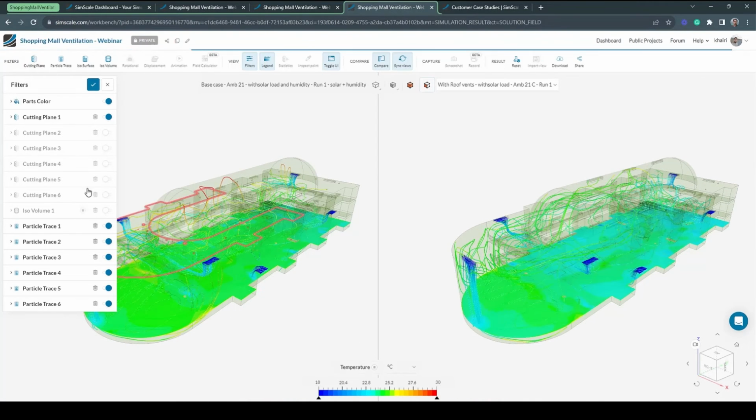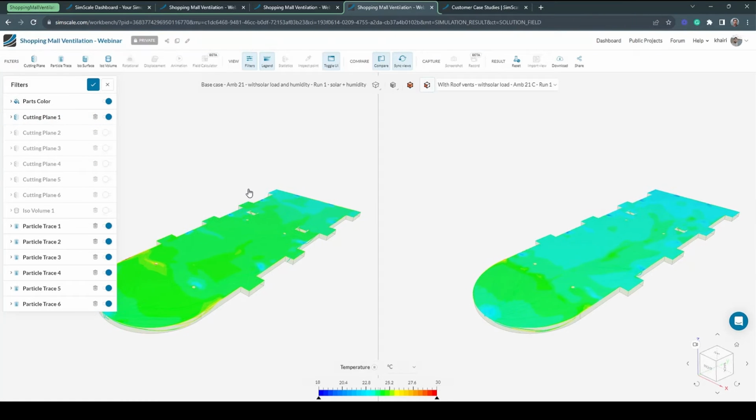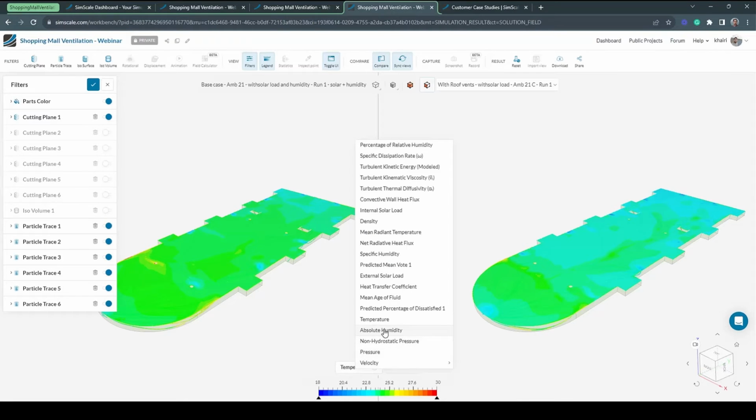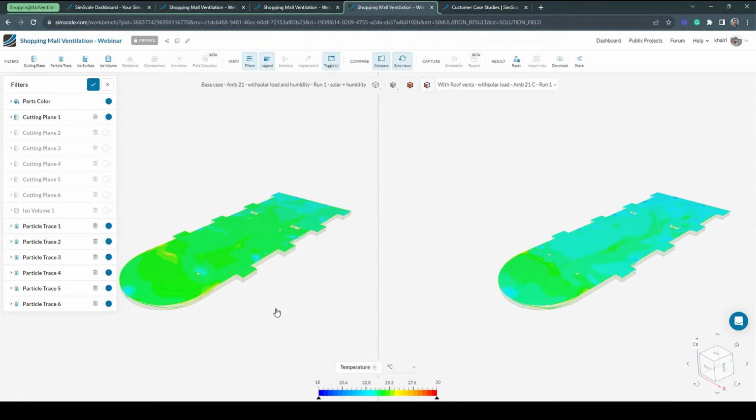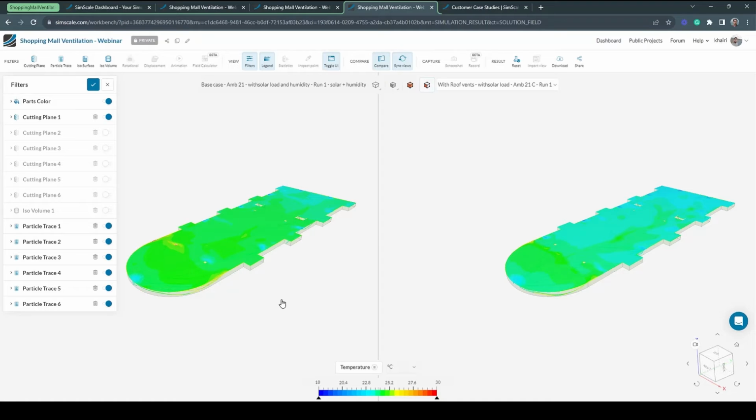And actually, this also brings me to the topic that with those simulations, the nice thing about CFD is that it really gives you the opportunity to investigate what is happening on a subzone level. So it gives you this information at every single point. What is the temperature? What's the velocity, the pressure, the absolute humidity, the mean age of air, etc., etc. So the potential of how CFD can be used to enhance essentially the overall thermal comfort inside the space, to improve the sustainability of a building design and so on, is indeed quite vast.